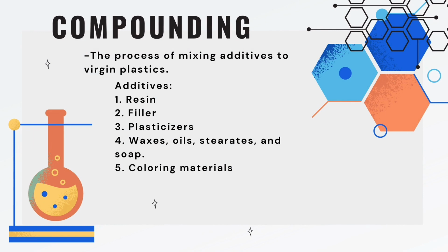Filler. This can modify the properties of plastics to give better hardness, tensile strength, finish, and workability. Fibrous fillers such as wood flour, cotton fiber, and shop rags impart improved mechanical strength to plastics. Asbestos increases heat resistance.